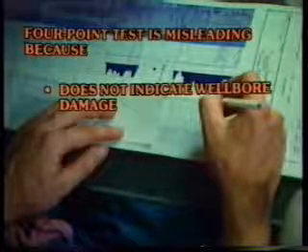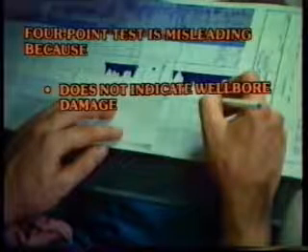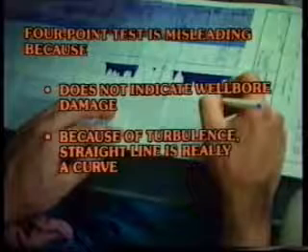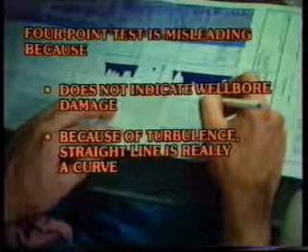The conventional well test and AOF plot are misleading because the test does not indicate the degree of near wellbore damage, only the well's productivity in its current state. Turbulence, which occurs near the wellbore, is rate dependent and causes the assumed 4-point line to be, in reality, a curve. The position of the line on the plot changes with the degree of stabilization.